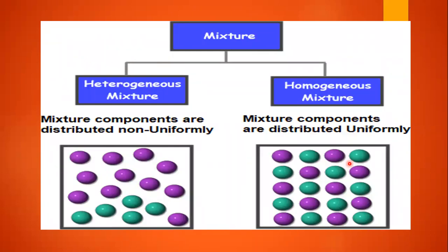If it is less than 1, there may be some incomplete combustion. Why? Because it is not going to reach high pressure and temperature. If this equivalence ratio phi is greater than 1, like 1.1 to 1.2, in case of a homogeneous mixture, in SI engines we need to maintain phi as 1.1 to 1.2. If the range is like that, that means a somewhat rich mixture, then we are going to have proper or complete combustion. That is the accurate value to have complete combustion.